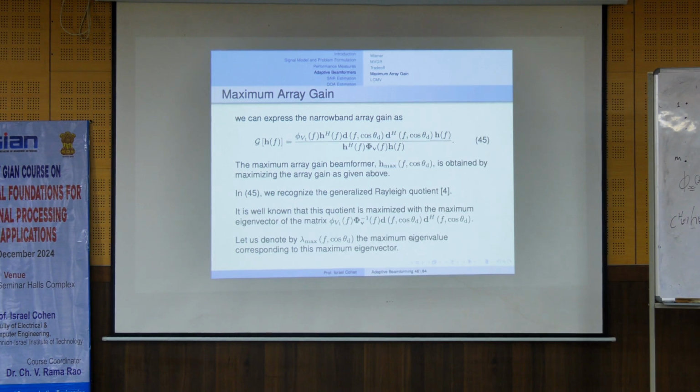Okay, for a fixed beamformer, we cannot define the maximum array gain generally because we don't know the noise field. So for a fixed beamformer, we define the maximum array gain for thermal noise, which is the white noise gain, and we define the maximum array gain for diffuse noise, which is the directivity factor.